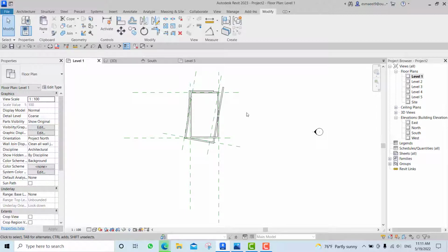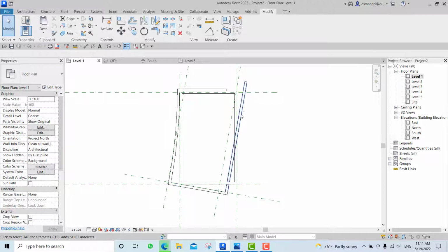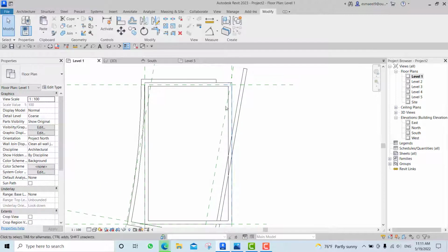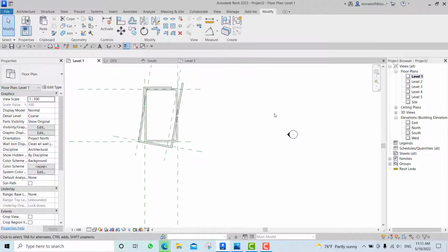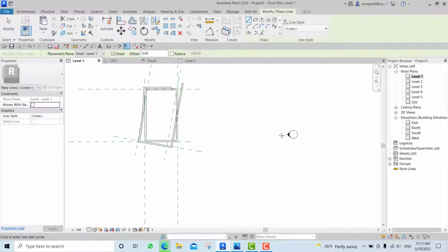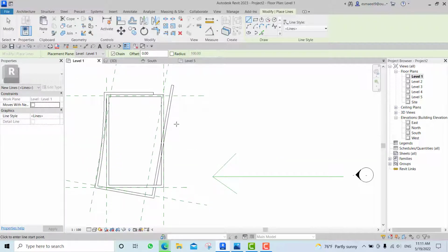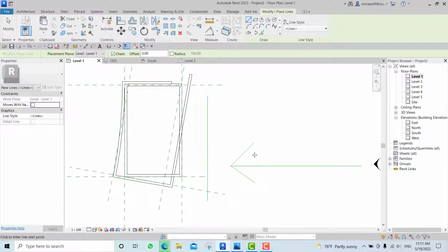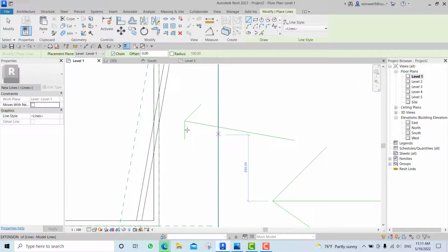The section we made, in order to be able to see directly this wall in front of us, like now if I just open this elevation, as you see guys, in this elevation, if I'm looking at this side, I won't be able to see this wall perpendicular. So what I want is to create a view to enable me to see it in this way.